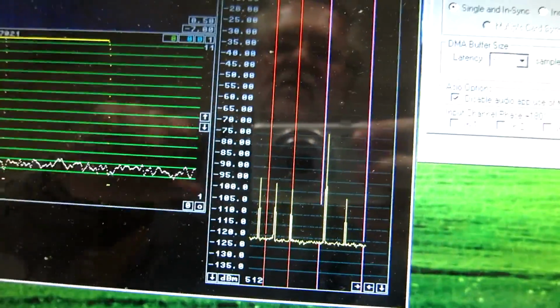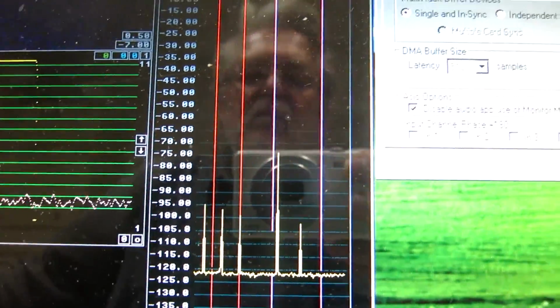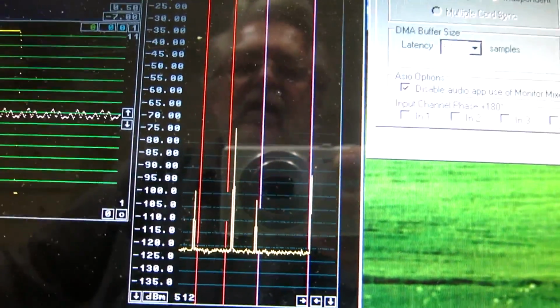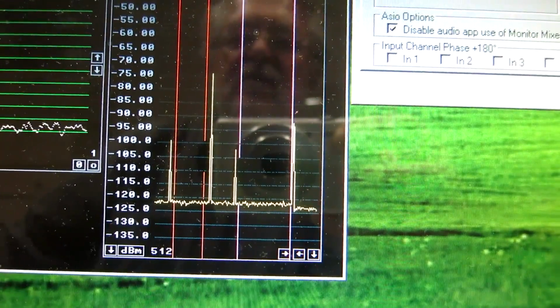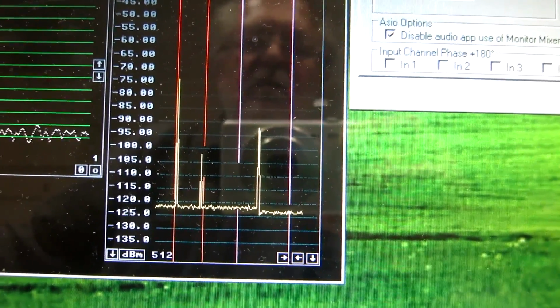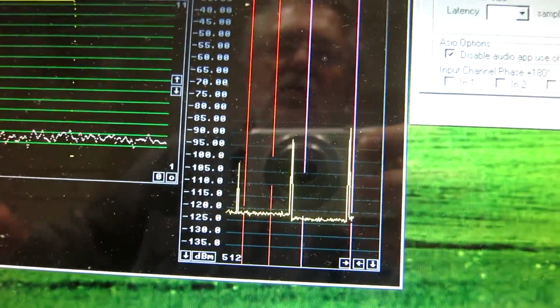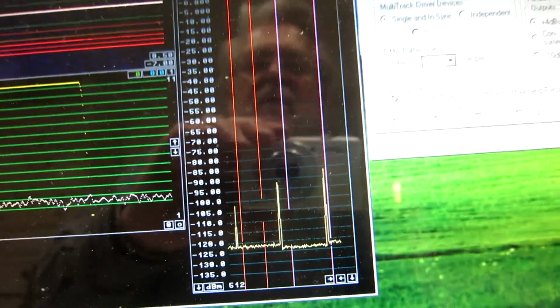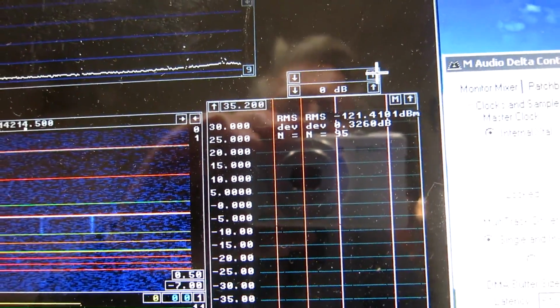Now we are 60 kilohertz above the signal. I remove the signal like that. And you can see reciprocal mixing is something like 2 decibels or maybe 2. And now the strong signal is back and I continue stepping upwards. Oops.